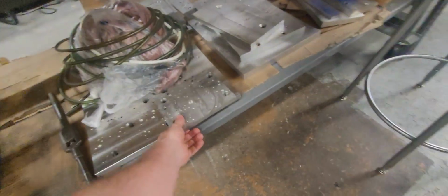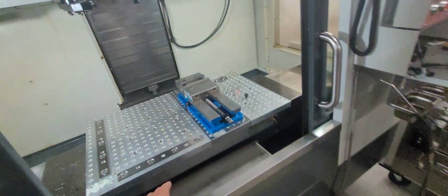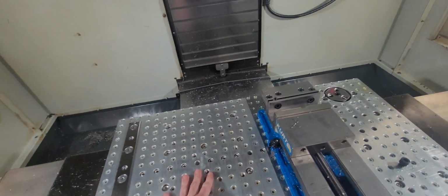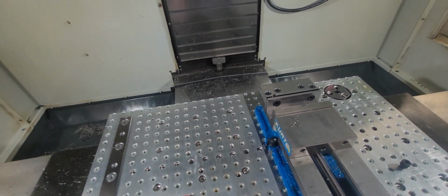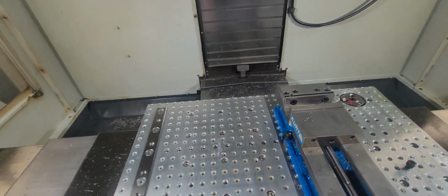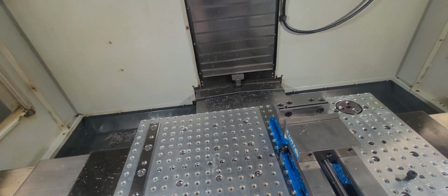So what we do is we set up all these different islands. This is the bigger island, smaller one, and these basically skim on here. I've got resident programs to just pick up a corner and skim it with my face mill to give it Z-true position, and yeah, that's how I do it, guys.